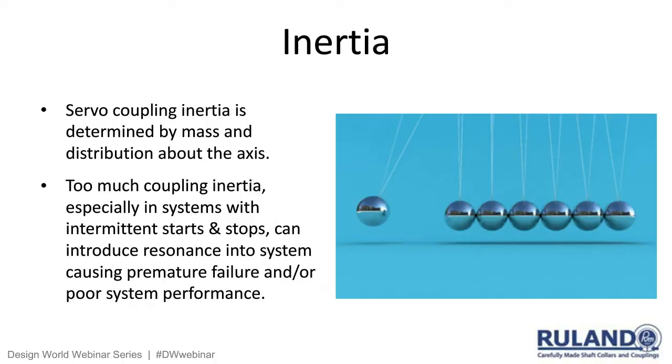Well, again, stainless steel beam couplings are much heavier than the aluminum versions, and it wouldn't be unusual at all to switch from an aluminum beam coupling to a stainless beam coupling, and now you've got issues with too much inertia. Your servo or stepper motors are tripping out. And again, this is an example of inertia causing issues and being a factor in your designs.